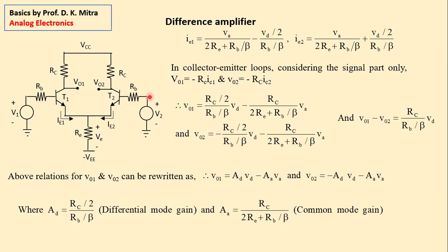So that the performance of the difference amplifier is not degraded much. Right? And our basic knowledge of this circuit shows that this input range here should not be more than VCC or less than minus VEE. That means not beyond plus minus 12 volt. Right? If you are designing or assembling a discrete amplifier like this in your laboratory with plus minus 12 volt, you will find the maximum input range is something like maybe 10 volt or so.